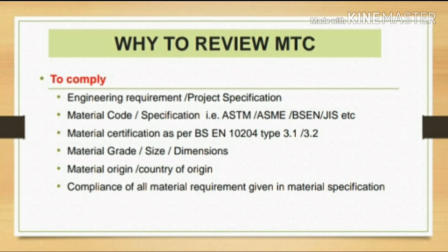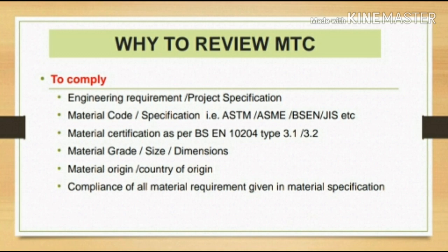So we have to check that also whether it is issued as per the type 3.1 or 3.2. Then general requirement like material grade, size, dimensions, country of origin, this should be complied as per the relevant material specification. And overall compliance of all material requirement given in the material specification needs to be complied while reviewing the MTC.